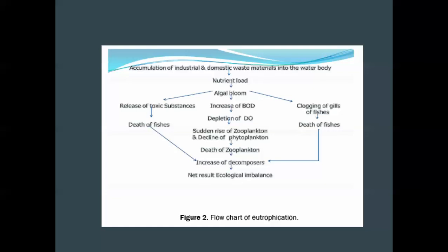Mostly phosphates, phosphorus compounds, nitrogen compounds, and as a result of this increase in nutrient load, the algae grow. These very simple plants grow, and in fact, they produce an increase in, let me clarify that, what they increase is the demand, the biological oxygen demand.